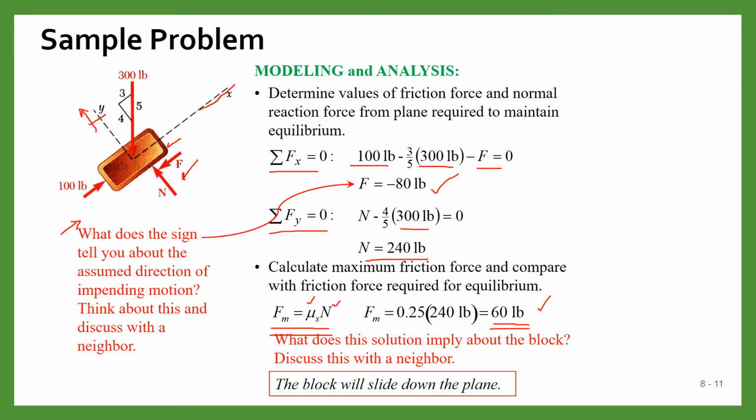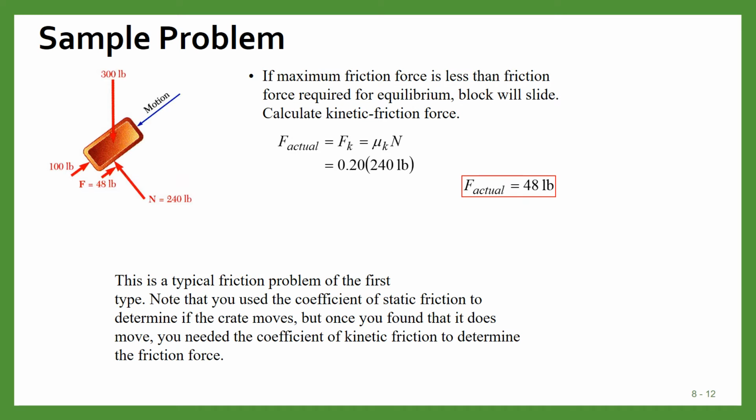So that means the block will slide down the plane. So if the maximum friction force is less than the friction force required for equilibrium, the block will slide.